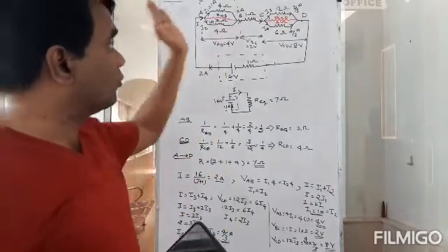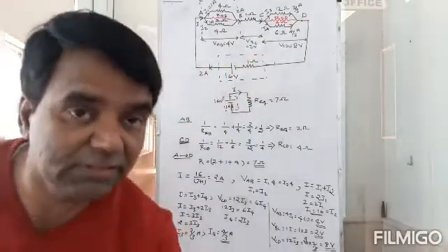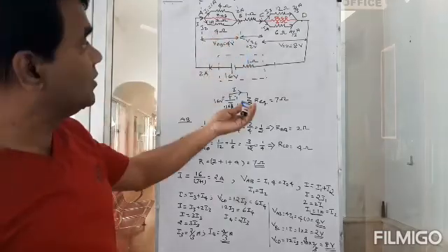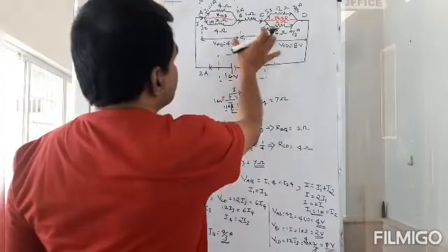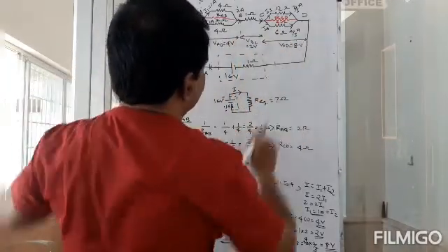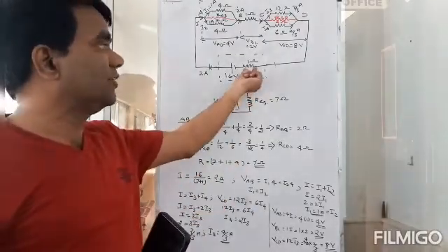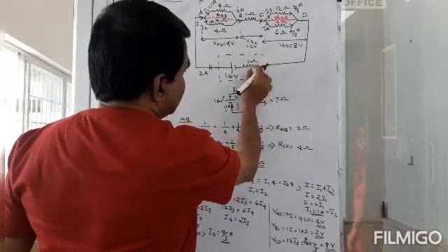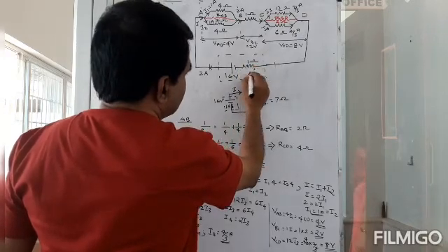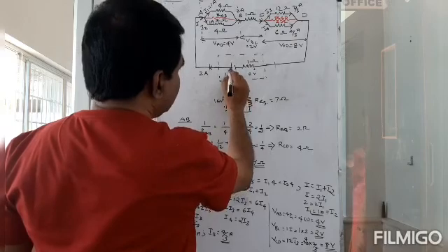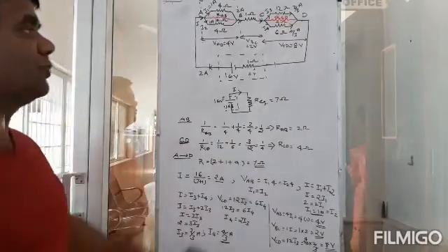But the moment current starts flowing in the circuit, there is going to be a potential drop inside the battery itself. Okay. So that will reduce what is available at the terminals. You see, only 14 is available from the battery. Even though the battery has 16 volts as EMF, 2 volts will get dropped here. See that, right? 2 amps come here, then 2 into 1 is going to be 2 volts here. So this is 16 volts minus 2 volts. So you get 14 volts outside.